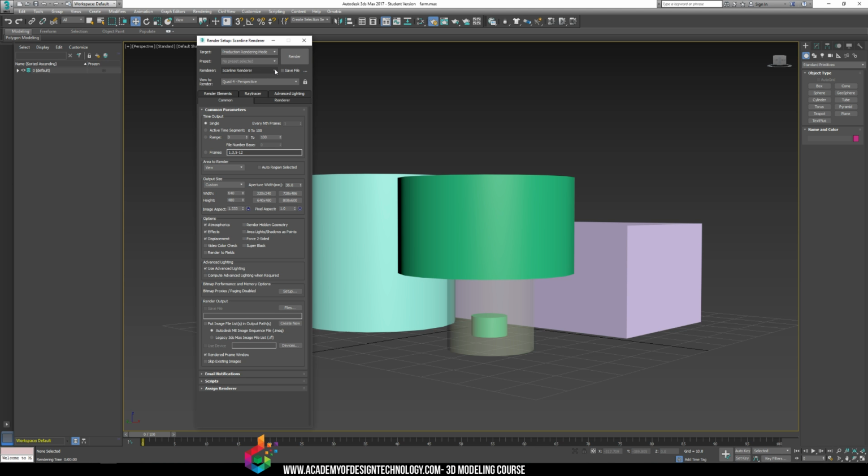So the basic renderer inside 3D Studio Max is what's called a scanline renderer. You've probably heard of different renderers online. Normally Pixar will make a new type of renderer for their movies. And that's exactly where they would switch that type of renderer. Right now we have Scanline renderer, but you can see we have Quicksilver, ART, View, iRay, and Mental Ray. Mental Ray is a very popular 3D Studio Max renderer, but we're just going to use the basic Scanline renderer for now, just so that we can send off this image relatively fast so that we can work with it. And that's pretty much it.